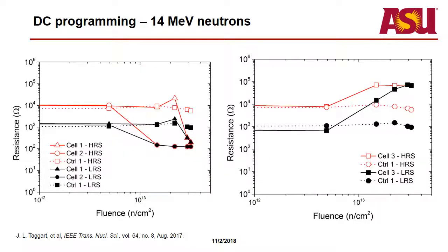And so next we continue on with neutron tests. So essentially this is a displacement damage environment with very little TID in comparison. In silicon, you'll have maybe 100 kilorad worth of dose due to secondary ionization in this process. But the majority of the dose received is going to be a displacement damage dose, so non-ionizing. And so here are 3 different devices that we tested. We tested a total of 5 of them in this manner.